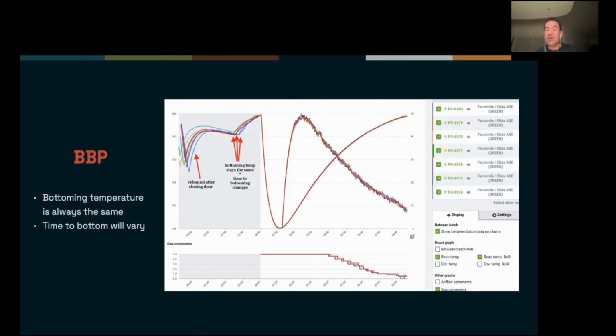So people get confused because they think that their machine is holding on to heat a lot more than some other machine is, but that's not necessarily the case. It could just be an artifact of where the probe is located and how much airflow there is where the probe is. And again, this BBP is just a hack. It's not indicating the drum temperature, but it is a way of manipulating the drum temperature.